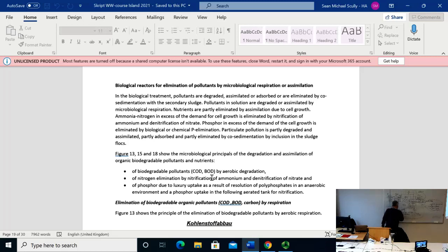The digestion means 50% degradation of organic material, and that doesn't include COD because most of the COD is eliminated in form of methane, but ammonia and phosphate come back. And because you have a dewatering, then the sludge goes away, and this is basically the filtrate. No? Okay. So it's all dissolved, no? All in solution.